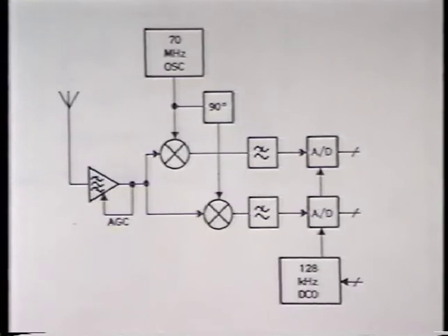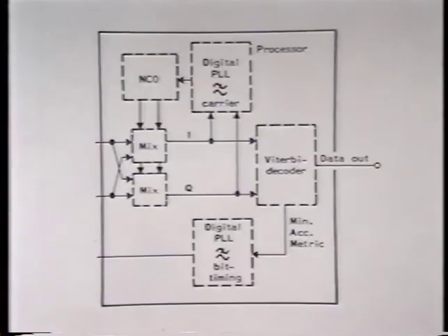This is the input front end to the receiver. After a constant signal has been achieved, coherent modulation is performed and samples are collected at 8 times the symbol rate. Anti-aliasing filters are also used in the receiver. After AD conversion, coherent demodulation is performed by a digital phase lock loop which performs tracking of the phase.